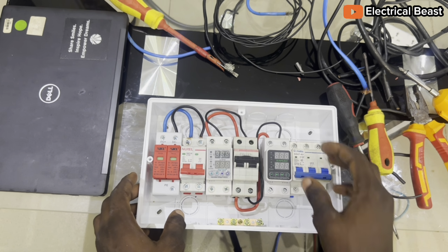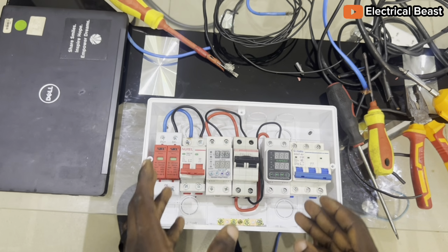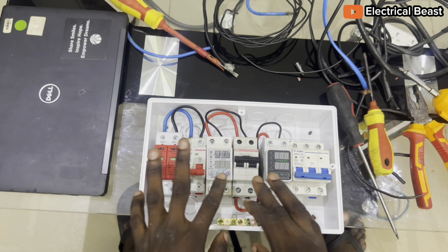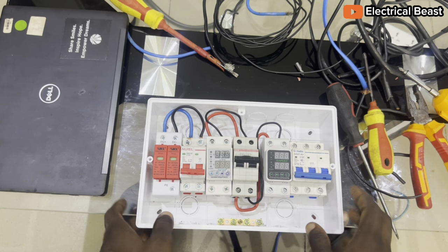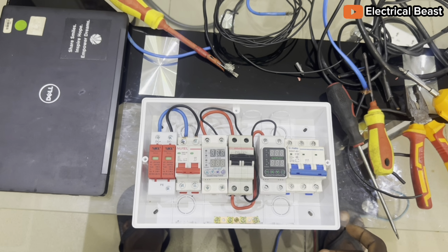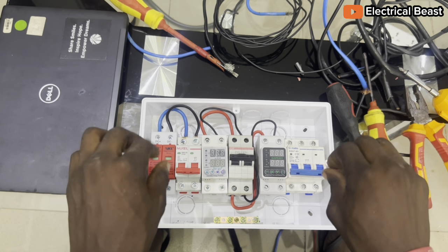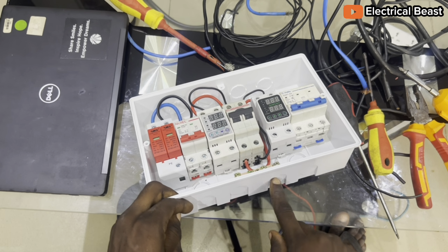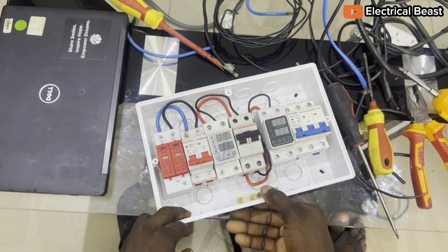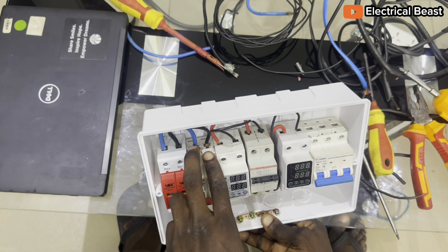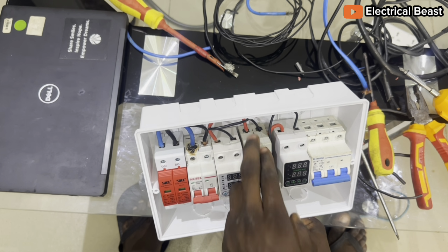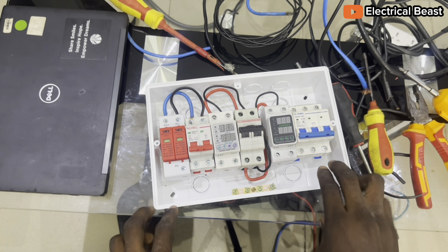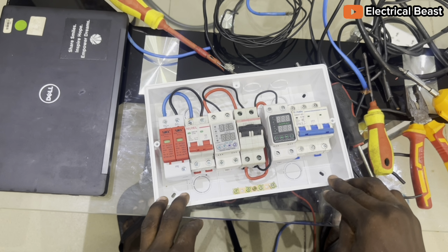Or some breaker boxes have two compartments, up and down. We have 4 ways up, 4 ways down. You can connect the breakers on top for the AC, then the breakers at the bottom for the DC. And as well, you can also do it like this if you prefer this method. Okay, so when you do it like this, you just have to lock the breaker box and put the screws to lock it. Then knock out these holes where you connect the input and the output. These holes connect the input from the solar panel. Then connect the input from the grid to this for the charging. Then you connect the output from this to the inverter, output from here to the charge controller, output from here to the DB. So that's it.